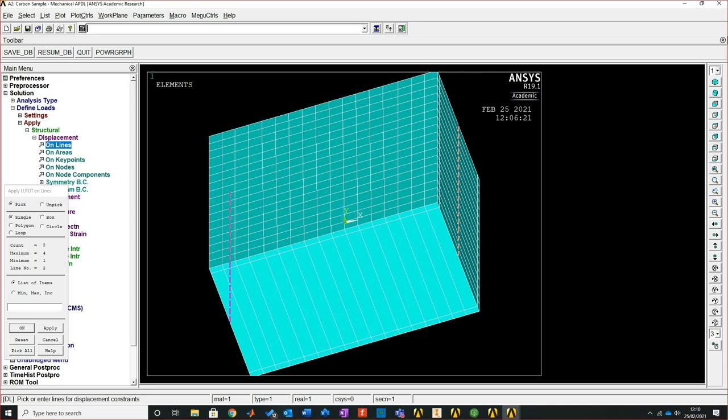This is because the nodes on here aren't classed as geometric lines. What it's actually doing is picking on the surface that we modelled. If you've got both dotted lines there to mark that it's been picked, click OK, and what you should get is your fixture marks.